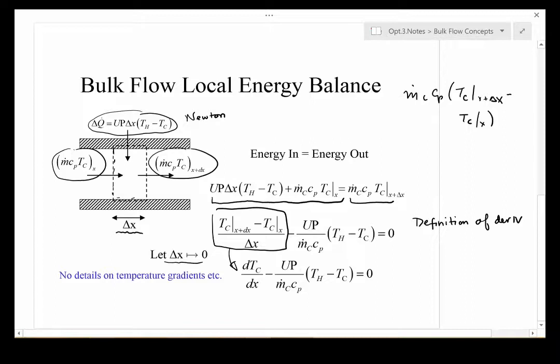So one of the things that you might ask is what happened to the conduction or the diffusion term. We'll show later on that these problems are formulated in something called the high Peclet number limit. The Peclet number is analogous to the Reynolds number. It's an average velocity or mean velocity for a pipe flow times the diameter divided by the thermal diffusivity.